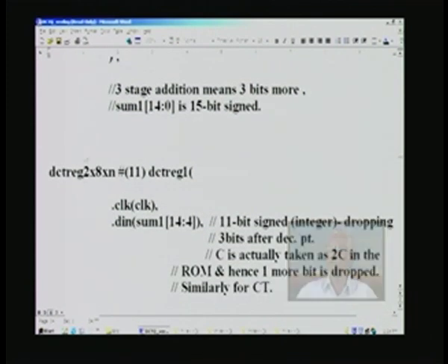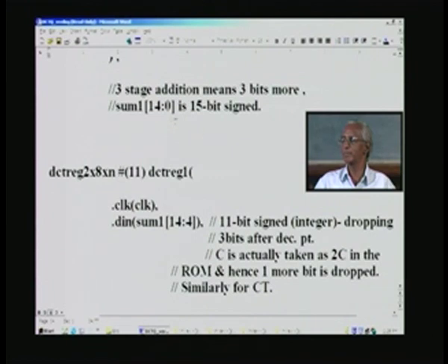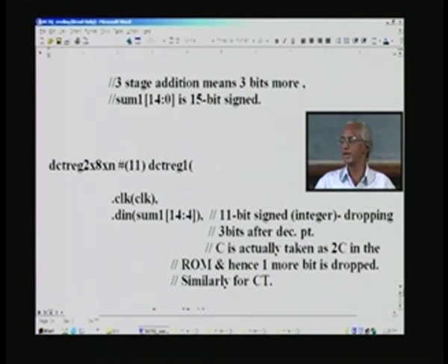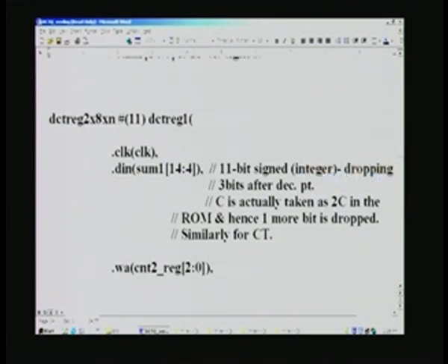This is the actual partial product P which we had seen in the algorithm before, and that is what this module is going to be doing. It has one input that is basically the same thing here, and once again we drop some more bits here, because otherwise it will become too unwieldy with the next stage, and anyway it is producing the desired quality. There is also a reason why we drop one more bit here. We will just have a look at the comments here.